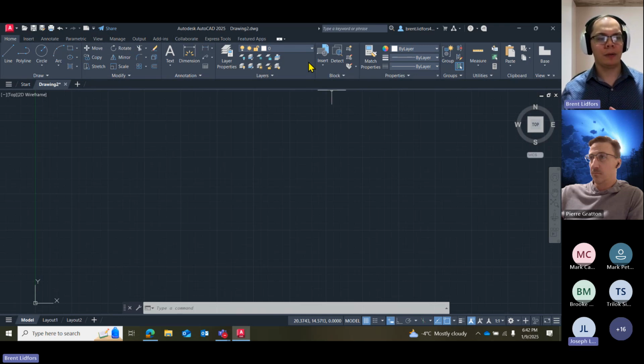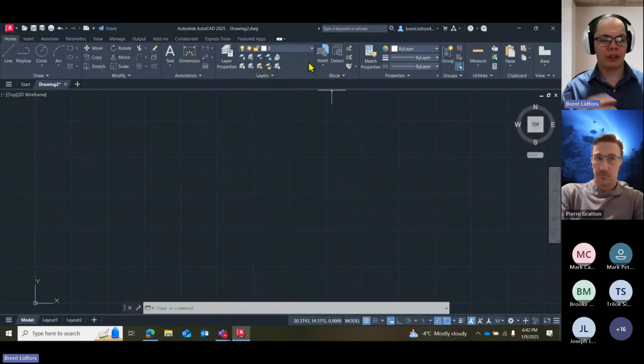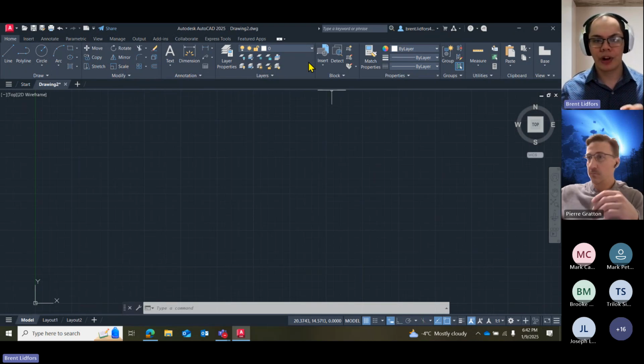So if I want to have a layer dedicated to plumbing, maybe I want to make all those lines blue. That can help me separate the plumbing lines from electrical lines or from just building structure lines in my drawing. So this helps segregate some of our lines from other lines in our drawing, to change their settings or to avoid accidentally editing them.